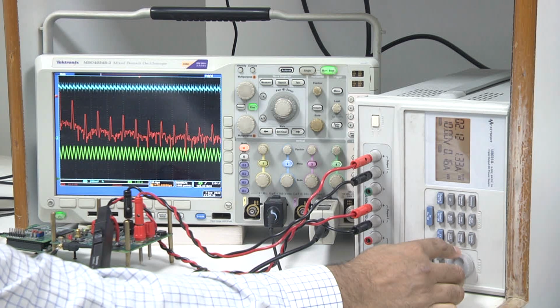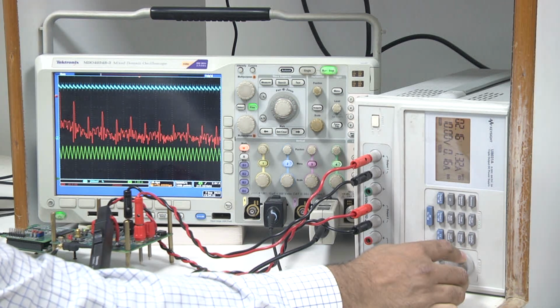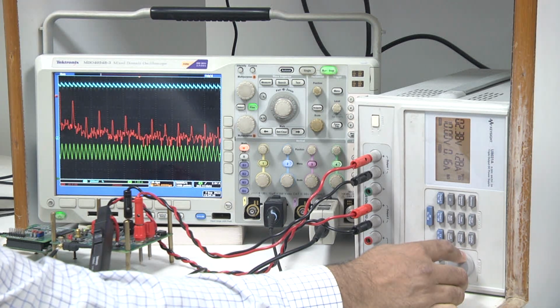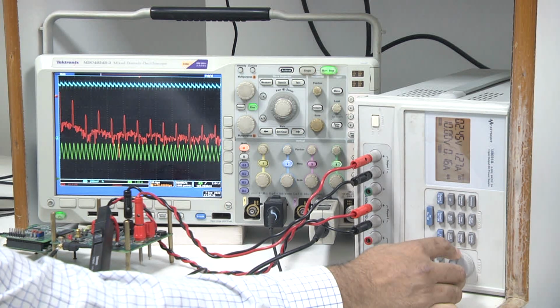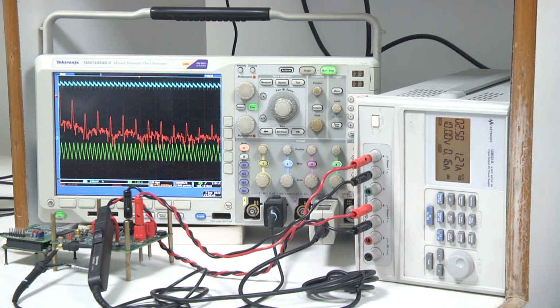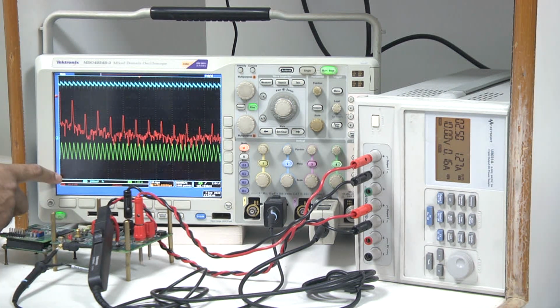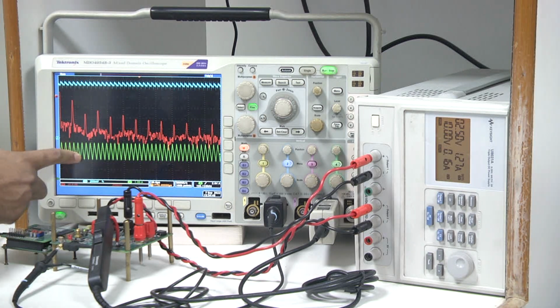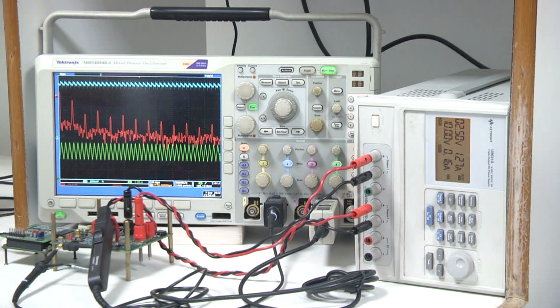Here you can see that we are first talking about constant on time valley current mode control. That means mixed signal current mode control, where the current loop is closed, and we are using a valley current of 2 ampere, and you can see that this division is 1 ampere. So this 2 ampere is the valley current. We are fixing the valley current.